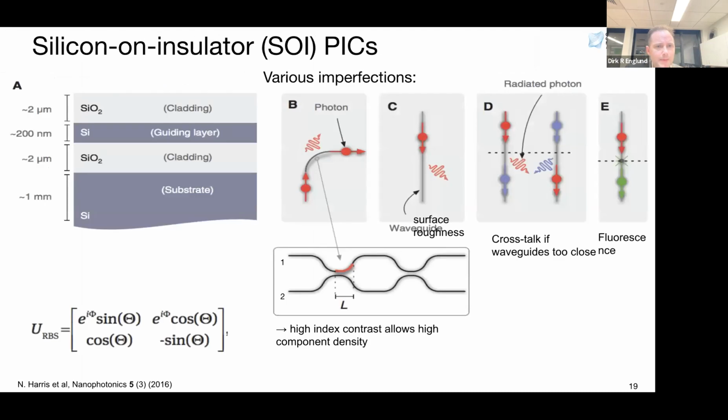All right, so now we're going to get into some more practical considerations. We had this waveguide calculator, and with that waveguide calculator, you should be able to reproduce the results that are shown here. So for example, if we want to make a single mode waveguide, let's say for the TE mode, you can go to the simulator and say, suppose you start with silicon.